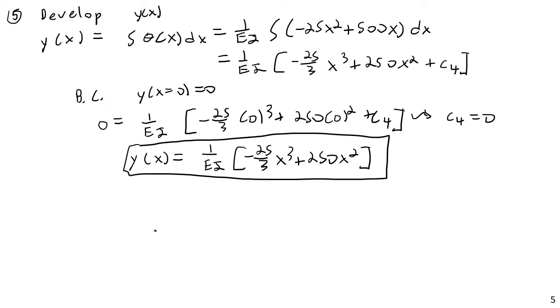So if I wanted to apply this, let's say I asked, what is the max deflection? Well, it's clearly going to be at the free end of the beam, max y of x at x equals 10, the end of the beam. So I can simply substitute that in.